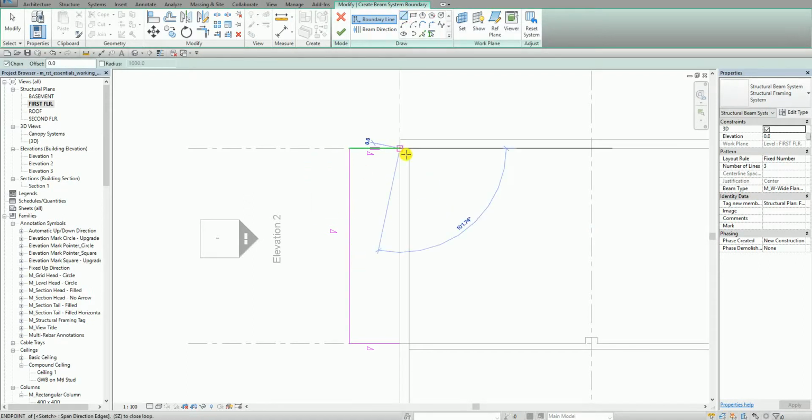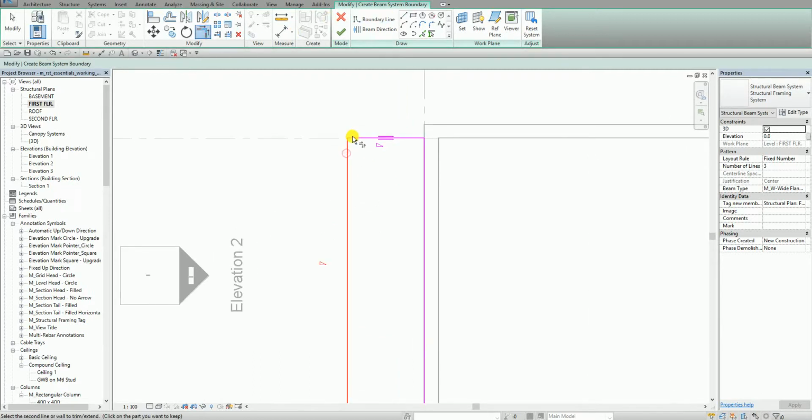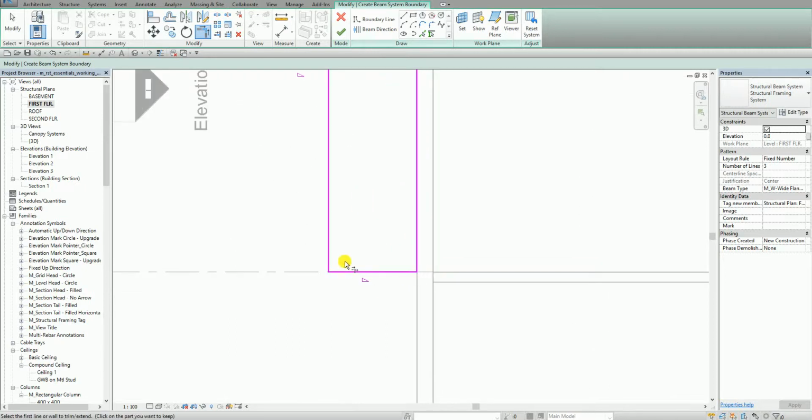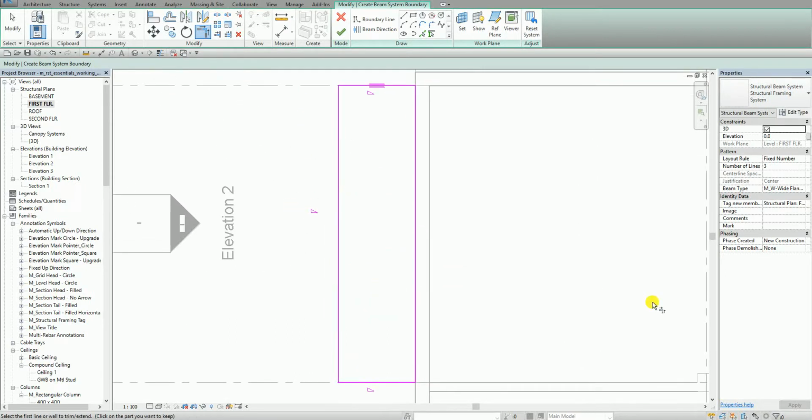Okay, I use the line tool because it should be close when you create the boundary of your system. Okay, so if required, you can use again your trim tool just to make sure it's close, right? So this one, it's already close, right? Okay, then after that, I select your finish again.